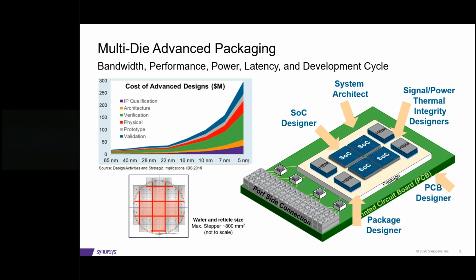As you're designing your die-to-die connections, you want to be able to provide feedback to your SoC design to tell them if it would be more optimal to put a microbump in a certain location, or at a certain spacing or pitch versus where it would traditionally have been placed with respect to the I/O, or where you would put your macros within the SoC, to get the most optimal die-to-die interconnect.